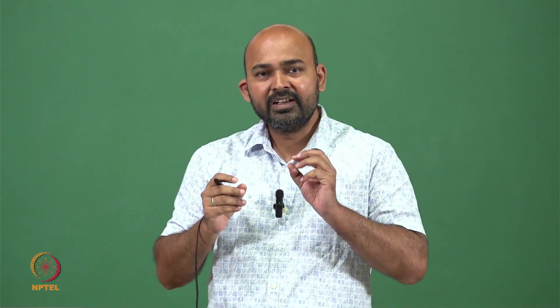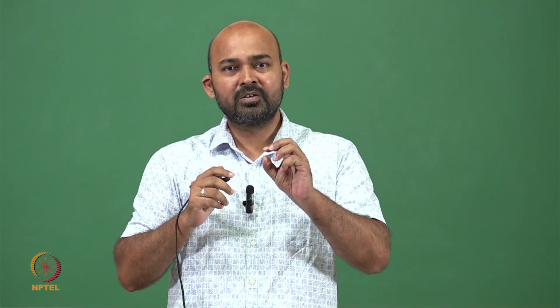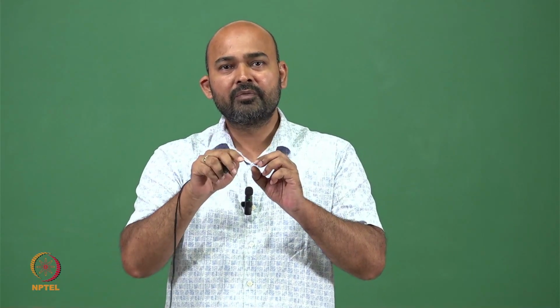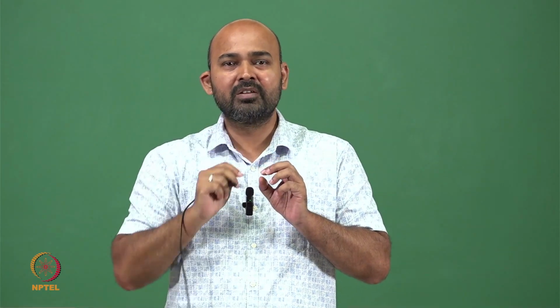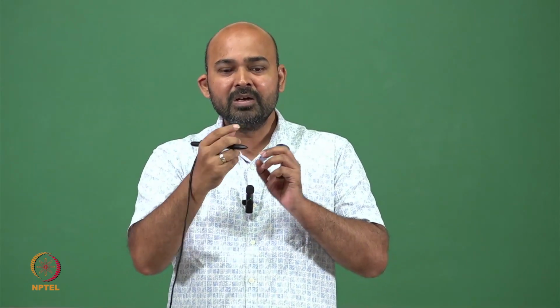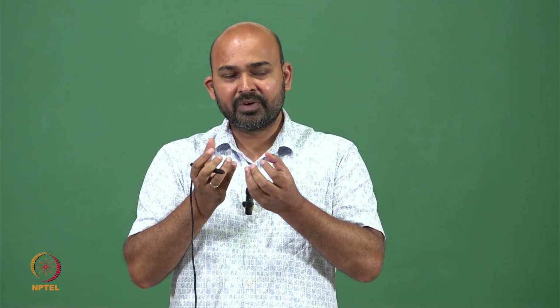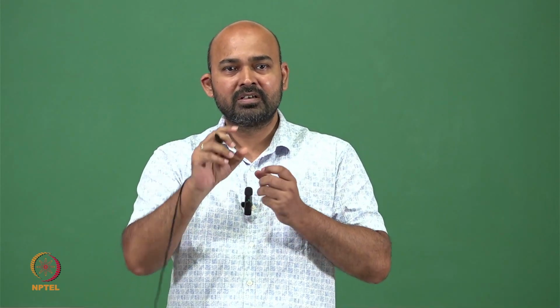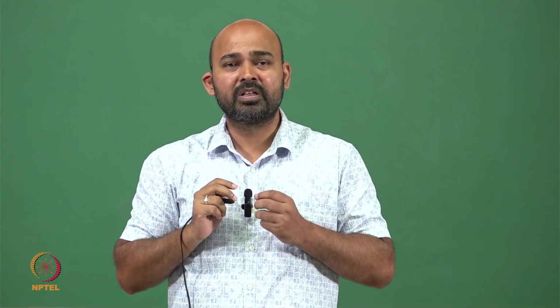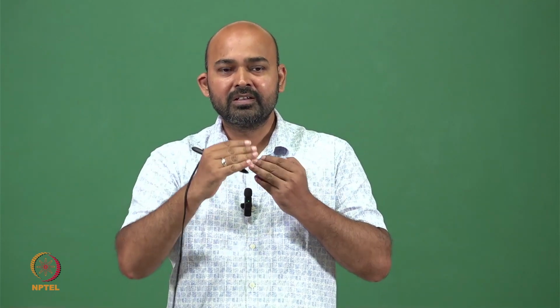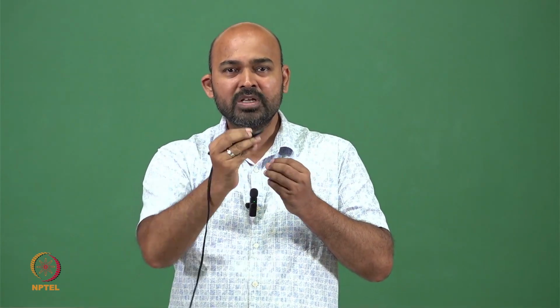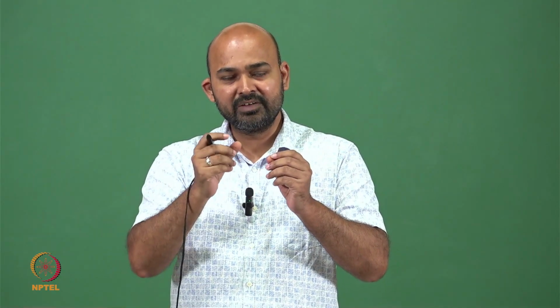So we are sending a known wavelength photon into the fiber, and we are getting a photon which is higher in energy. It means this photon has received some energy somewhere in the optical fiber. So depending upon the difference of energy, we can find out the temperature at that point in the optical fiber, and that point we can calculate based on the round trip delay of this photon between when we send and when we receive it.